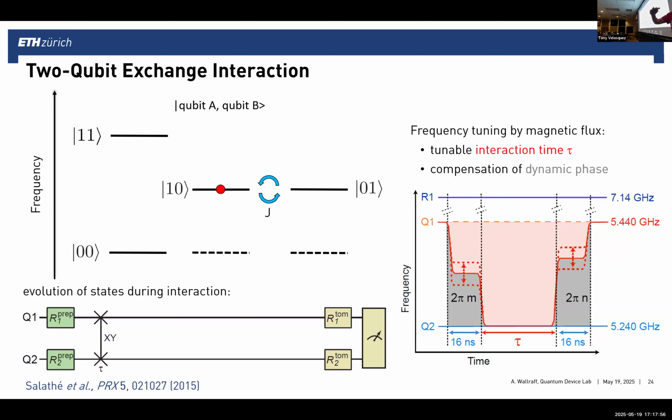So if J is fixed and you have some finite detuning, which will always be the case because one qubit stays at a fixed frequency and the other can only go so far away, if you tune it down in frequency it can go to its minimum value, and if you tune it up it can go to its maximum value. Your effective J in this nominal off state will still be finite, and this will lead to a so-called finite ZZ coupling between your two qubits.